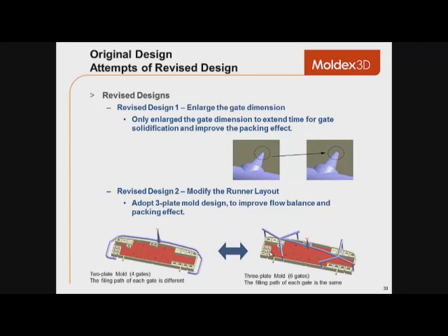For the first revised design, we decided that we should enlarge the gate dimensions to extend time for gate solidification and improve the packing effect. And in the second redesign, we modified the runner layout to improve flow balance and the packing effect.